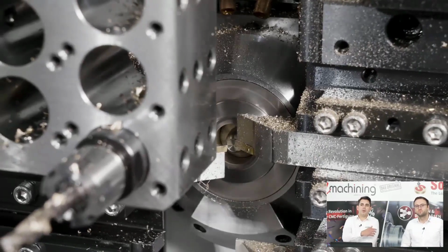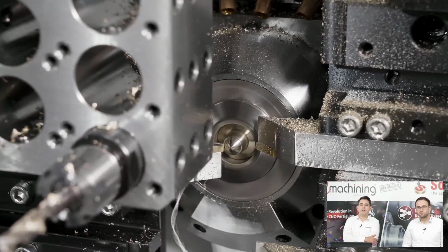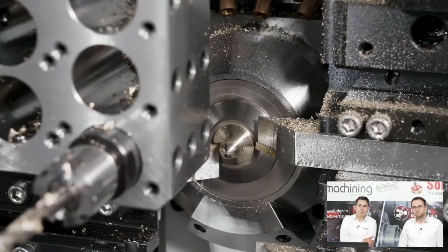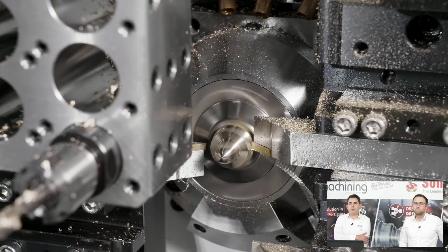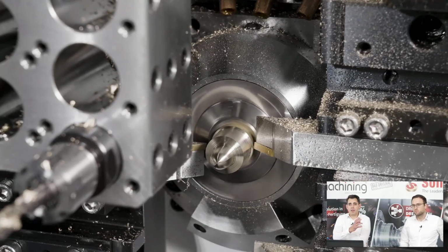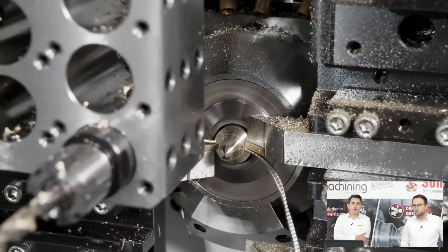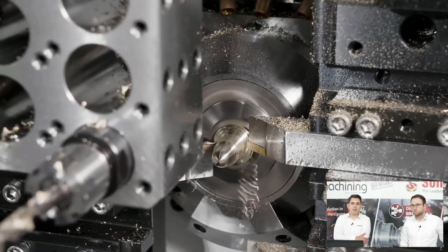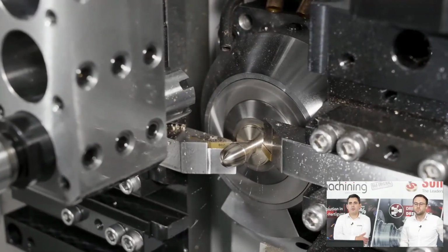Yeah, we can see here now the superimposed turning with two tools together. So at the moment only one, but in the same position we are using the same feed rate on both gang tool posts, but we will have a good example when using the second Z-axis of the gang tool number 2 to machine with two different feed rates. So we are seeing the same position.